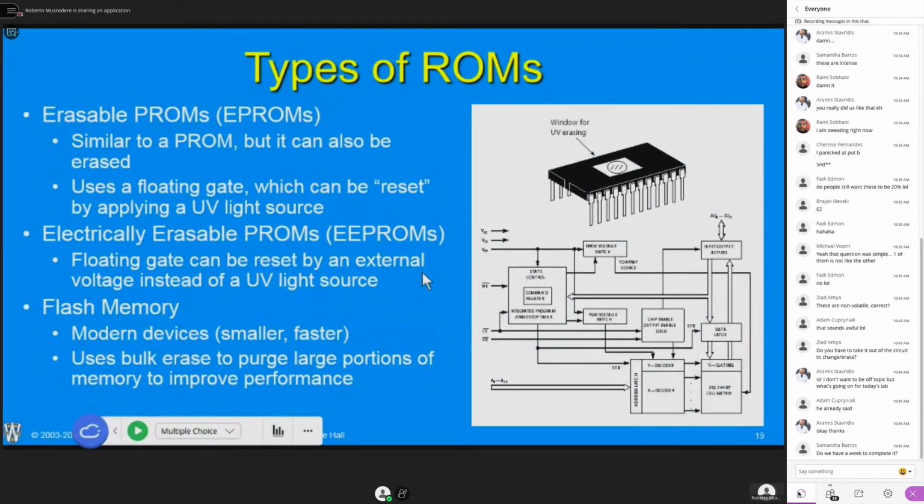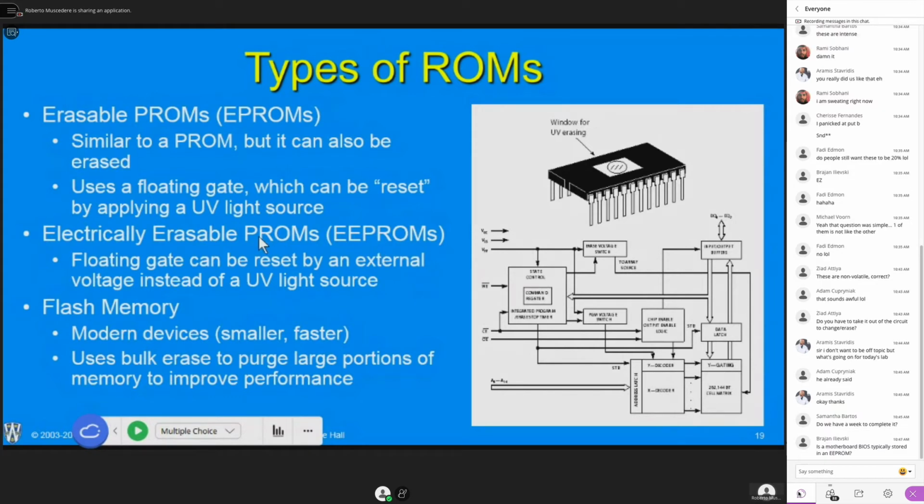Now, again, it's not usually super fast. It's slower than the standard read cycle, but at least it can do it without any real special circuit modifications. Okay, so this is what we typically use now. Your motherboard, again, it's usually about cost, so they use flash memory, which I'm going to get to. Now, where an EEPROM is good is when you need to change very little things at once. EEPROMs are usually called NOR memories when we talk about them in today's day and age.